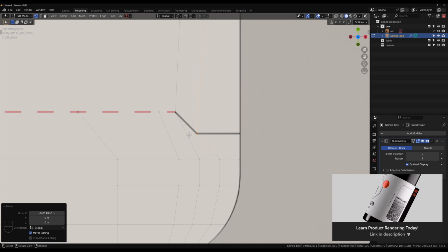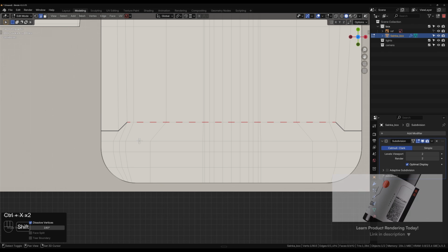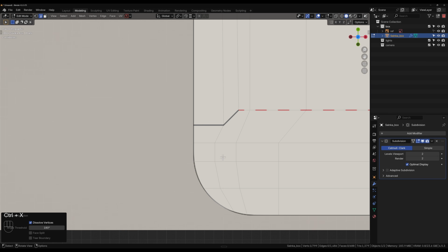And what I'm actually going to do is rip it so that I'll grab these, Control X, grab that, Control X. I'll grab you, Control X. You're just going to select the first one, then Control click the last one. It'll select the shortest path.